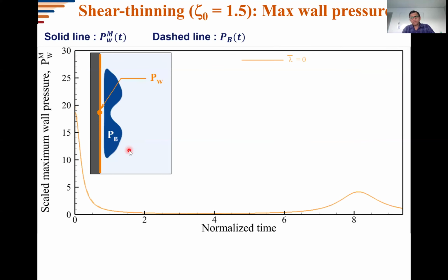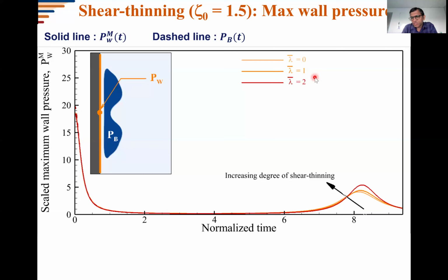And one of key interest in these kind of things is basically the pressure that is observed at this wall. So if we look at what is the maximum pressure that the wall experiences, then it would look somewhat like this when the material constant is 0 or the effective viscosity of the fluid is the highest. And as one increases the material constant, one observes that there's increase in the pressures that the wall sees. So there's higher jet velocity and higher damage potential.